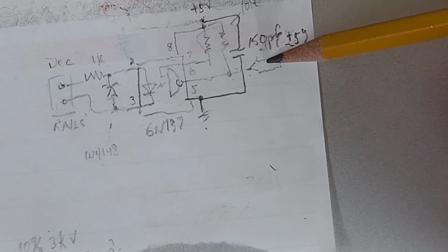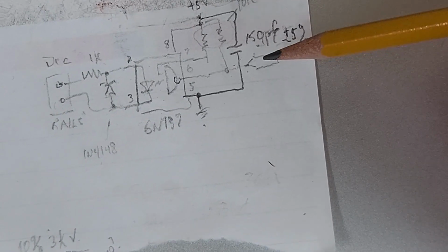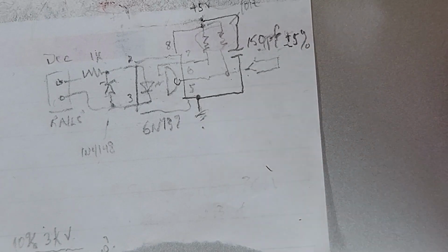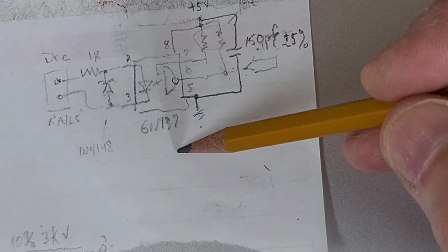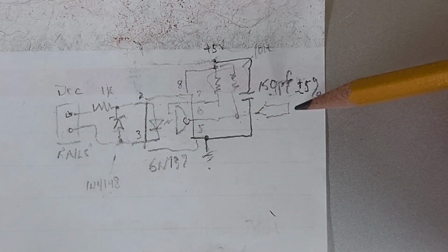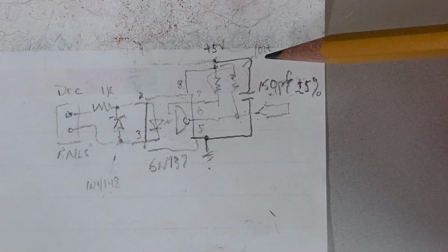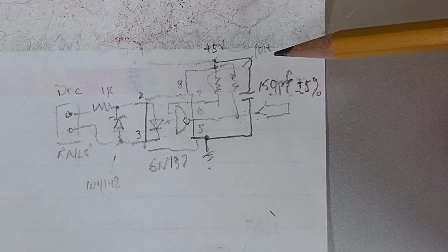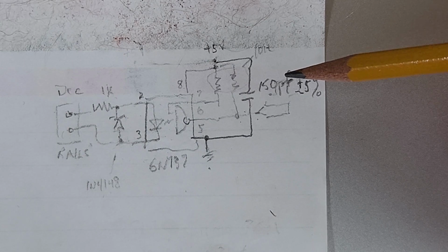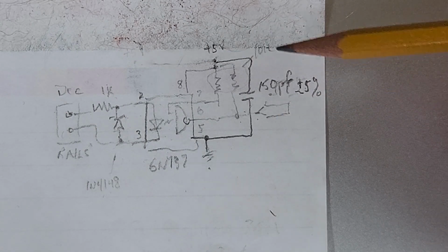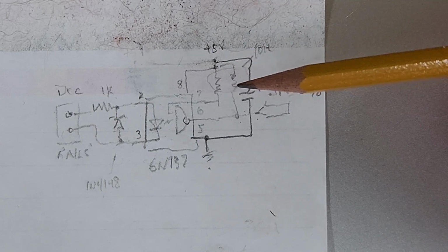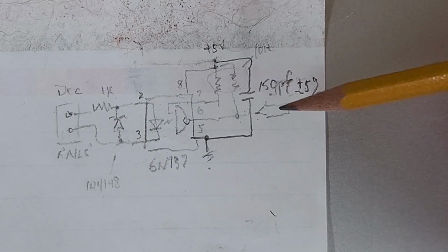And so here's the output that's going to the Arduino, and the Arduino is seeing this on its input, and the input is looking at it as a rising and falling edge, and the rising edge and falling edge are being used to gate a timer on and off, and the timer data is being used to correlate to a duration. And as it was stated earlier, the duration of the pulses is what codes the ones and zeros.